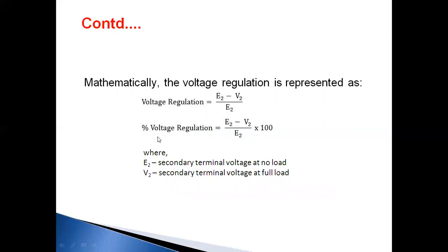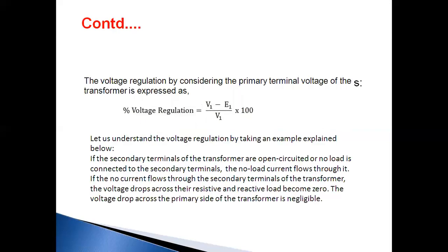So the percentage of voltage regulation is nothing but (E2 minus V2) by E2 into 100. But E2 is generally known as the secondary terminal voltage at no load, and V2 is the secondary terminal voltage at full load. This is the mathematical expression of voltage regulation.